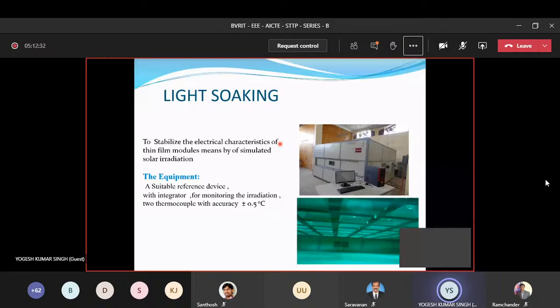The first step is the concept. In the concept, we will go around on-grid, off-grid, and hybrid kinds of systems. The second step is the pre-feasibility study, where we decide the conditions, the shadow effect, and all those things. Then we cover the feasibility study, where we cross-check the irradiation, the temperature, the humidity, and the wind speed. Then we discuss those parameters around the design and development, and finally we do the construction. So these are the important parameters.